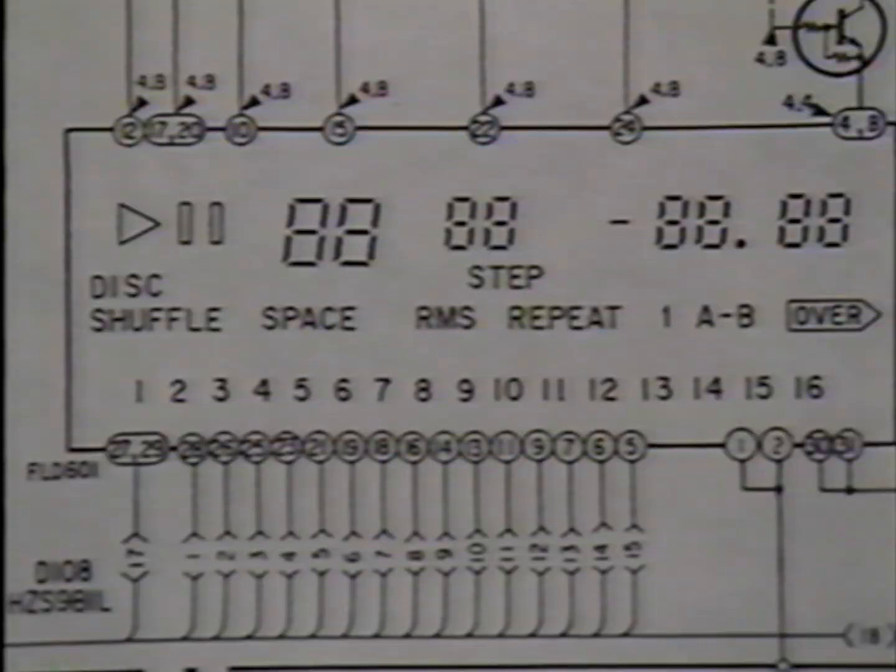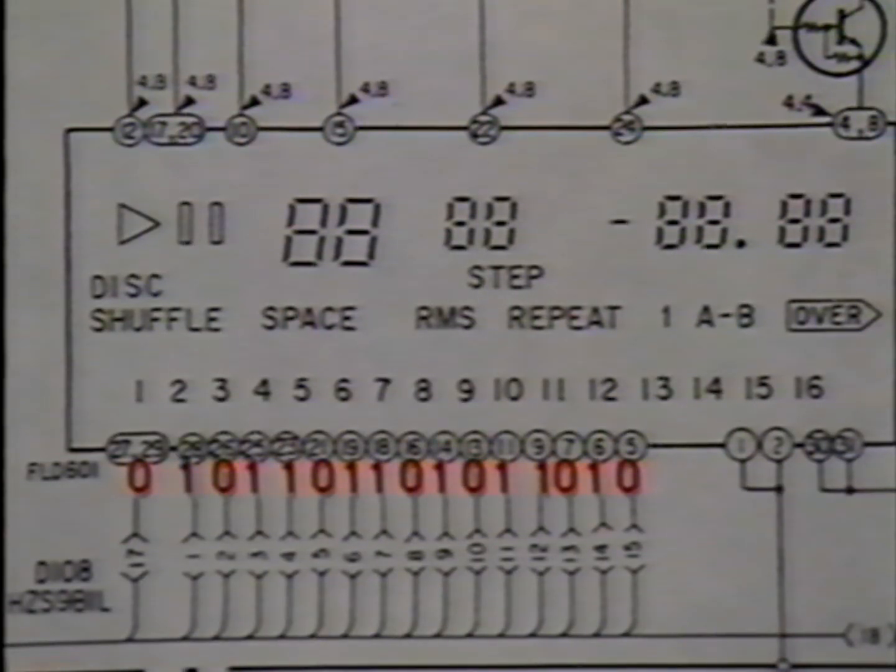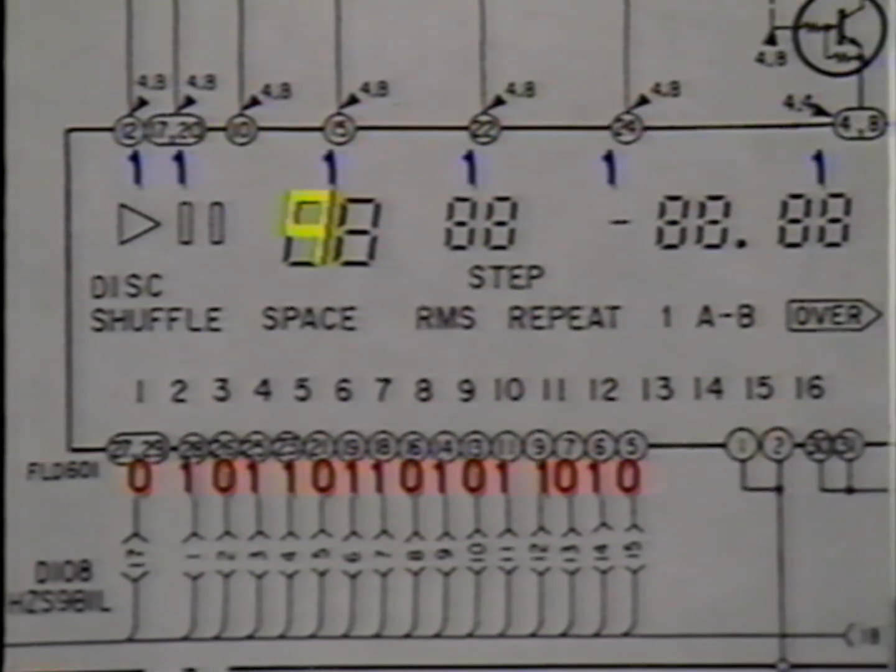The display's message is created when the microprocessor outputs the segment pattern for the first character to be displayed on the segment output lines. The microprocessor then outputs highs on all grids except that of the first digit, which is supplied a low. This low turns the first digit on and the character is visible.